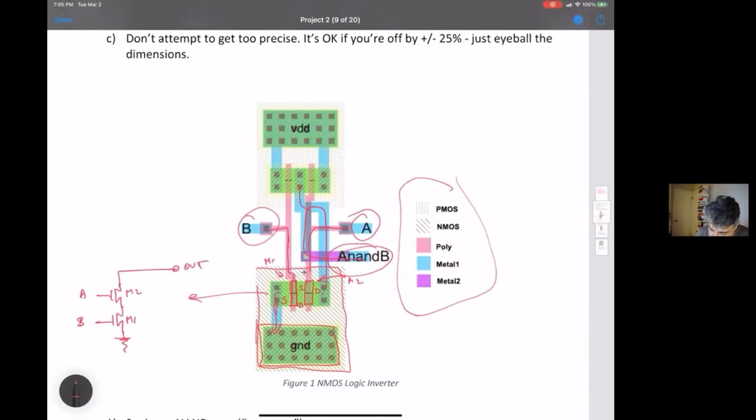So this is out. And the PMOSFETs, here's one PMOSFET. Again, this is poly. Anytime poly goes over active, it's a gate. So poly going over active, gate. These two look to me like they're in parallel because this is the source of one of them and the source of the other, and these are the drains that are shared. Let's call this M3 and this M4.